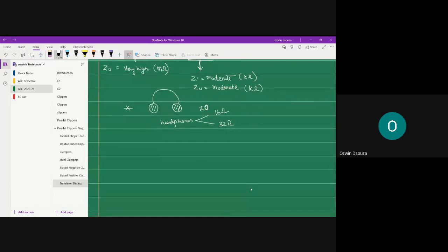What exactly are you doing with your headphones? You have your mobile phone, and you connect your mobile phone to the headphone through a 3.5 mm jack. Now, does the headphone have any amplifier circuit? No, it does not. Your mobile phone has an amplifier circuit in the device, and the mobile phone's amplifier will have some output impedance.